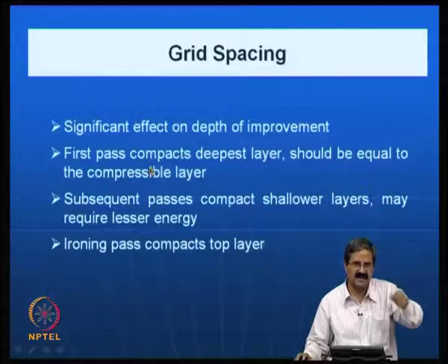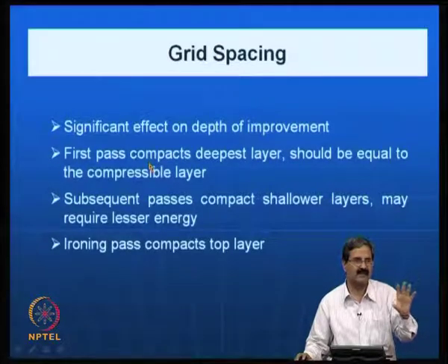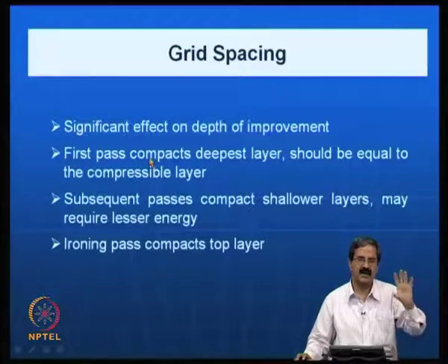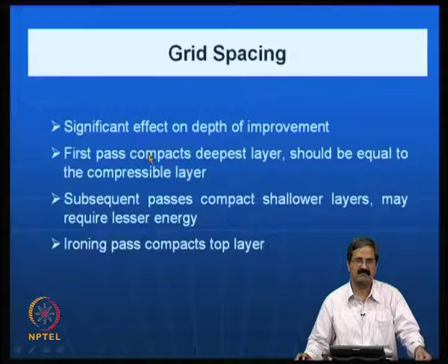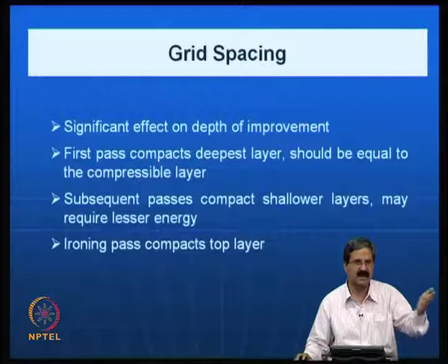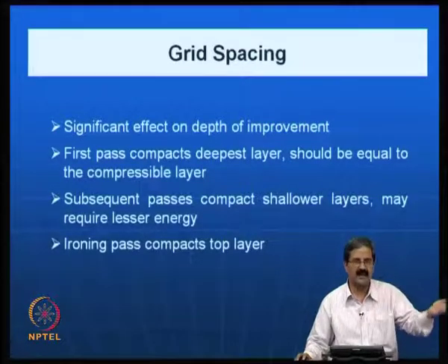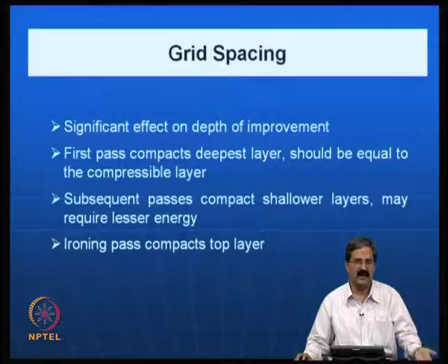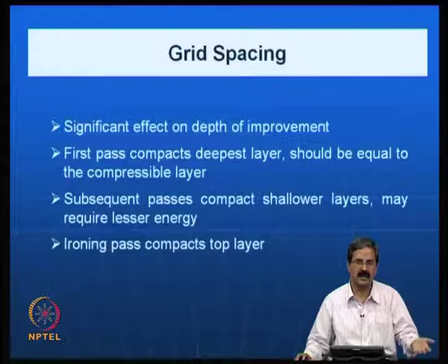What happens? Shear strains get mobilized in the soil system. So you must be able to do a numerical analysis, a finite element analysis, or some sort of detailed analysis, where you impose a load and calculate the strains, say strains of the order of 0.1% or 1%, some sort of limit, similar to the depth of pressure bulb concept. If the stresses are going very deep, definitely you can't do a stone column or any ground improvement technique up to that depth.